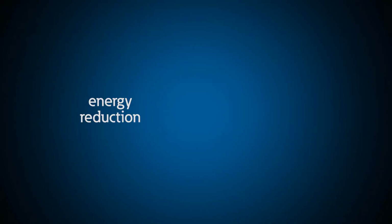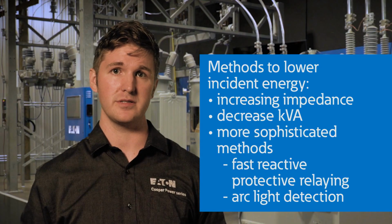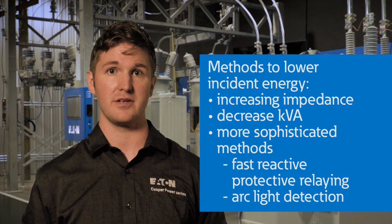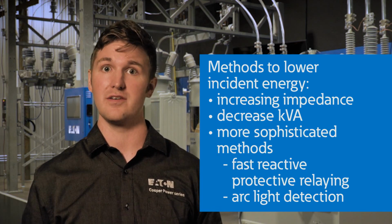Energy reduction, on the other hand, involves lowering the incident energy by reducing the available fault current or the clearing time if a fault were to occur. This can be done by raising the impedance, lowering the kVA, or via more sophisticated methods. For example, fast reacting protective relaying or arc light detection can de-energize the transformer quickly in the event of a fault. In any event, all arc flash energy reduction methods aim to lower the incident energy at the transformer output, typically the low voltage terminals.